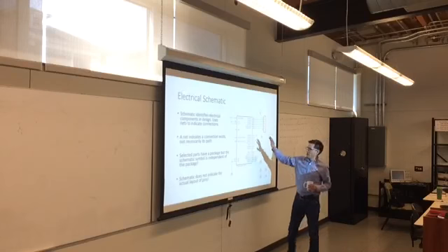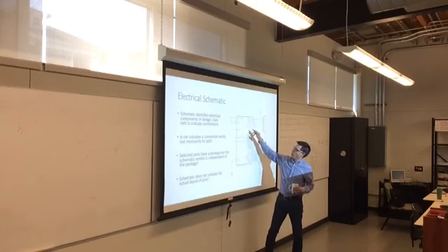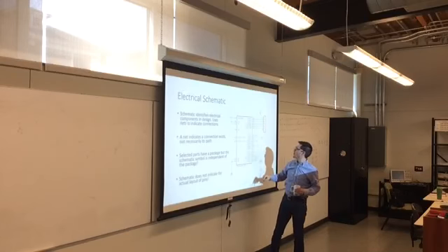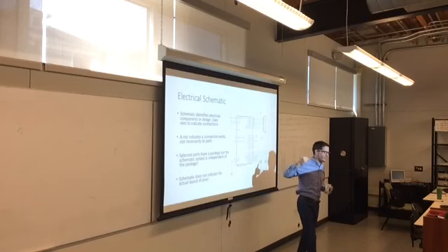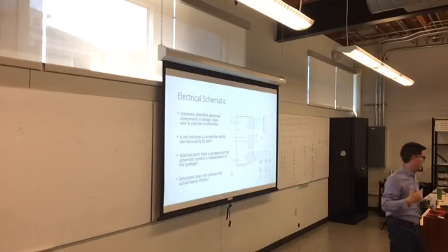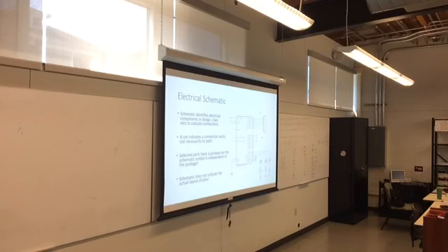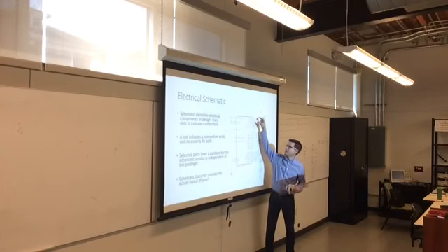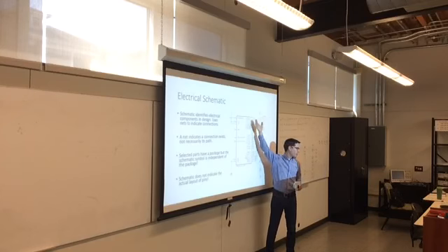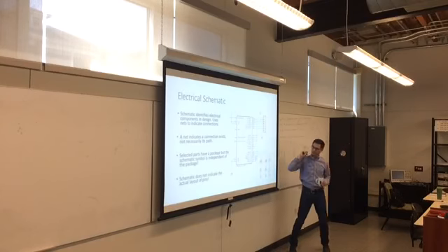So here, this chip is laid out with pin 1 here, and pin 2, 3, 4, 5, 6 over here. They're not physically like that on the chip. That is not physically how the pins are laid out on any of these chips. It's laid out that way logically, because it's grouped for you to help route things together. Here are all of the port C pins. Well, let's just put them close together logically so we can route them out to a header.